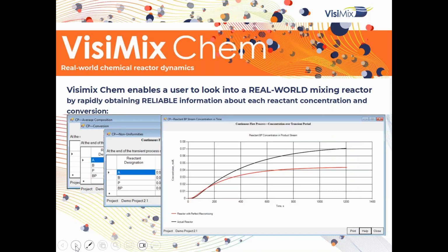And other kinds of results that you will see: a concentration as a function of time, where we will always present two graphs. One graph will be the reactor with perfect macro mixing, that I explained before, that we see as homogeneous, but maybe the local diffusivity will be different between the materials. And we'll present the other graph, which is the real result, when we take into consideration the maximum diffusivity or the complete diffusivity that happens in the tank.